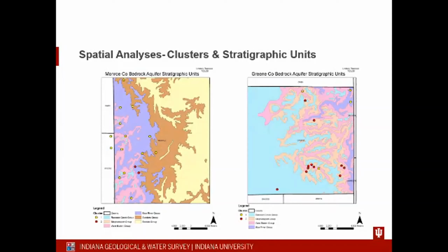The Raccoon Creek group of Pennsylvanian age is mostly comprised of sandstone and shales with limited amounts of limestone. It's also typically a fairly limited groundwater resource, so more sites collected from this region will hopefully help form a clearer picture of the aquifer capacity and its influence on spring chemistry. The Stephensport and West Baden groups fall under the same aquifer system of Mississippian age, and those are greatly composed of limestone and just some sandstone with minor amounts of shale. And these groups are also more heavily characterized by karstic conditions.